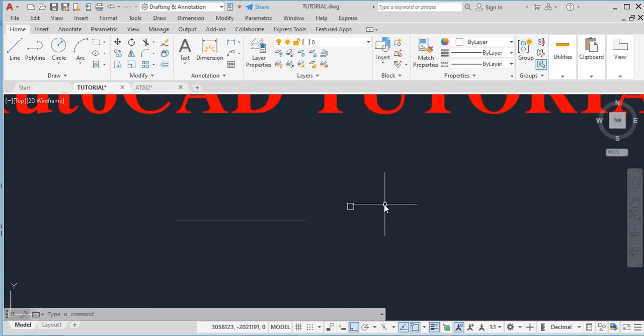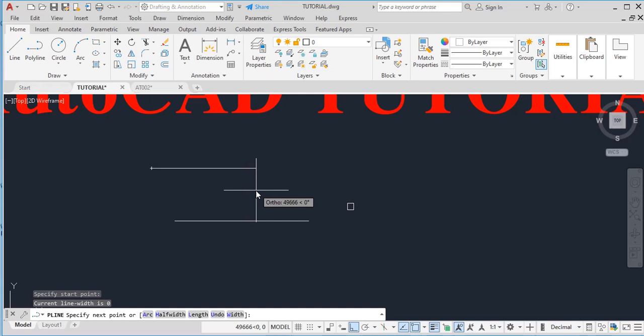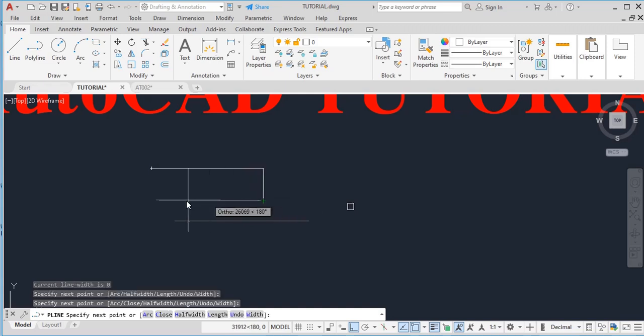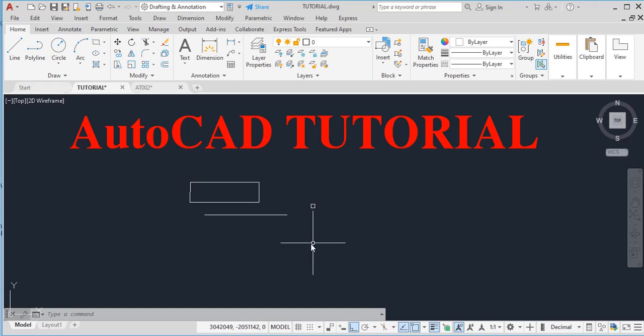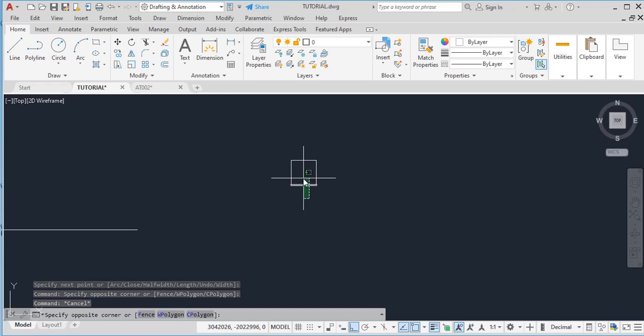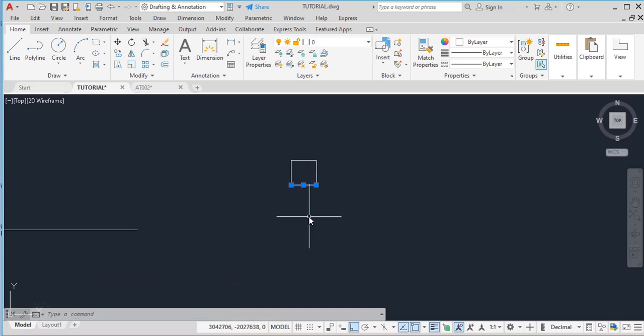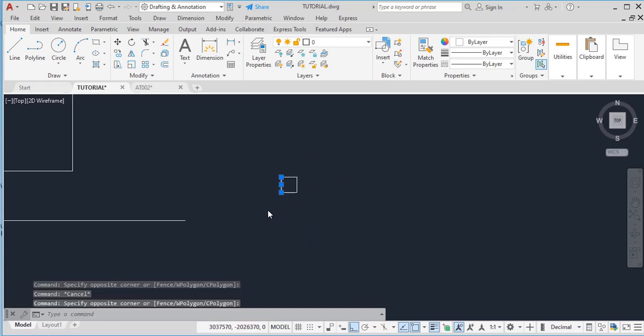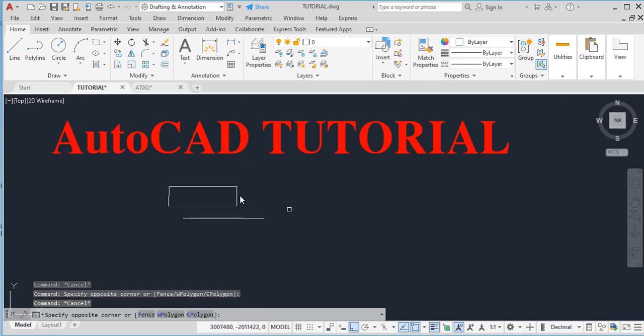The second type of line is polyline. So we are going to pick polyline next, clicking on the first point, second point, third point, fourth point, as the case may be. Now this is the polyline. The difference between the polyline and ordinary line is that the polyline will always appear as a block, all right? But if you do that with the ordinary line and select one part, you see they are all individual elements, it is not a block, but the polyline is a block.